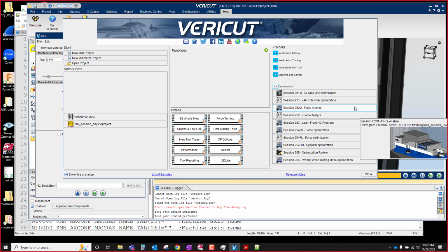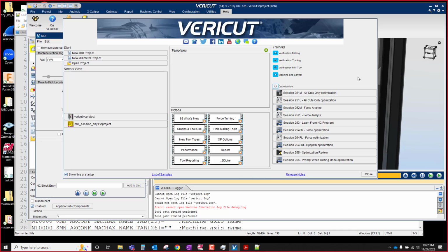I've recently been bringing in a lot of the higher-end models for my tools, with the cutting edges on. I use the 1.5 inch AXD Mitsubishi all the time. It's one of my favorite tools for roughing. For a while I would just make it a bull mill, put on the radius and call it good.